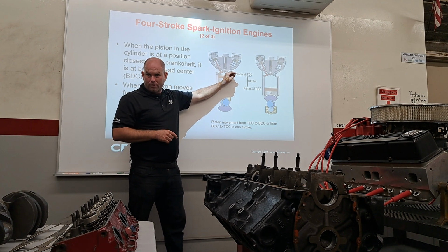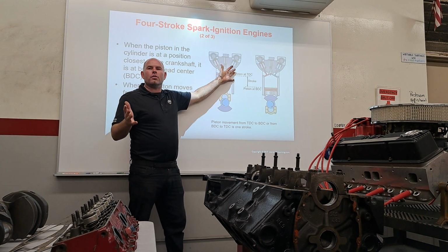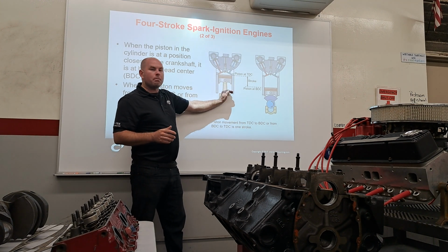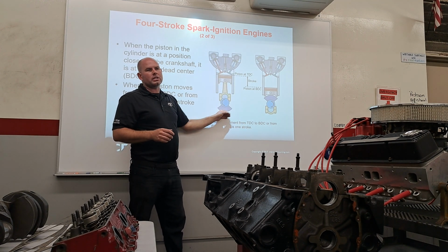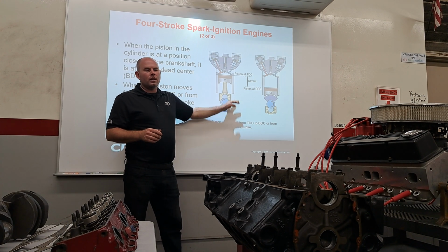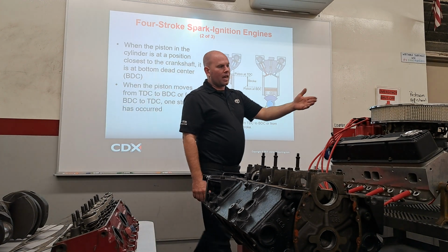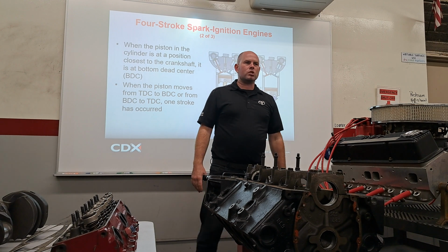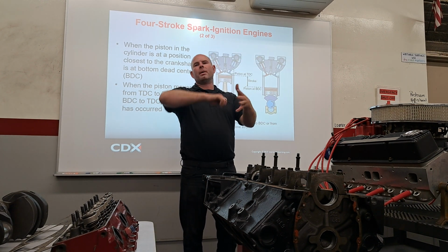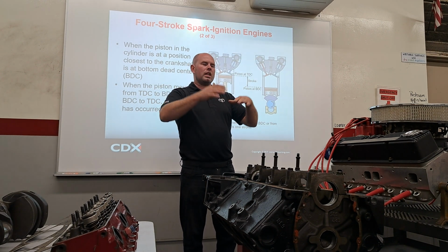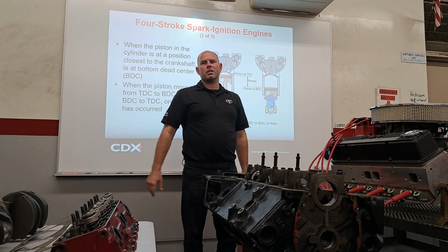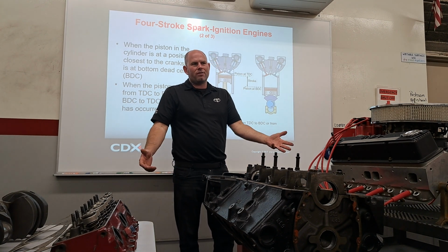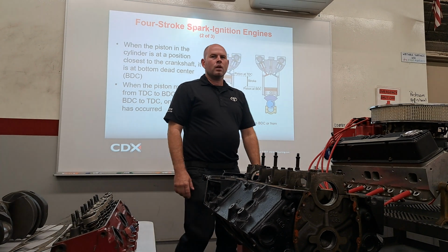Oh, I don't know. Genuinely, I don't know. The crankshaft is at the same point at TDC compression and TDC exhaust. I'm just letting you know. So the next thing I could do is look and see if any valves are open. If the exhaust valves are open, I'm like, oh crap, I gotta do another 360. And when all the valves are closed and that mark is lined up, I know I'm at TDC. For whatever reason, if you need to find TDC, now you know.